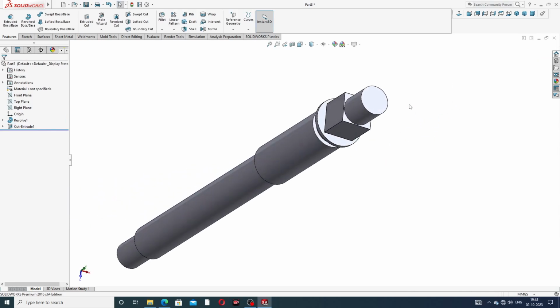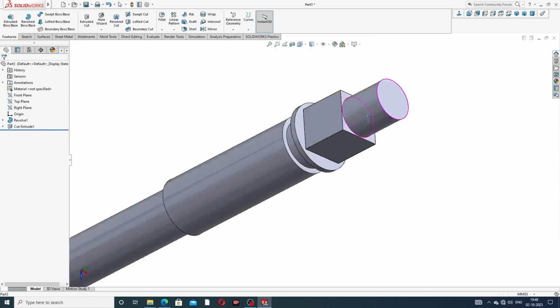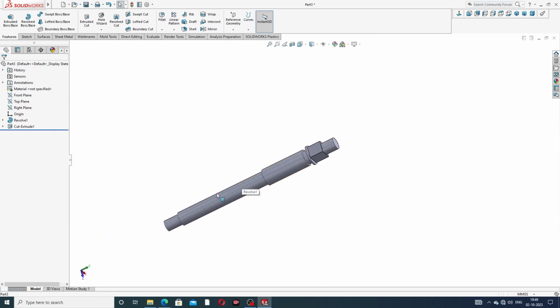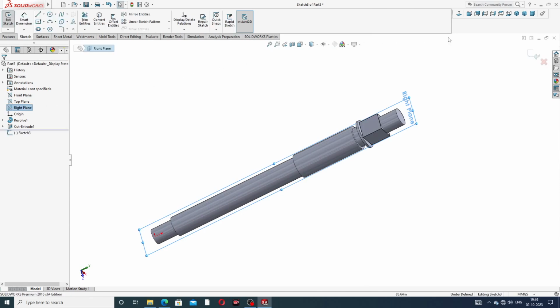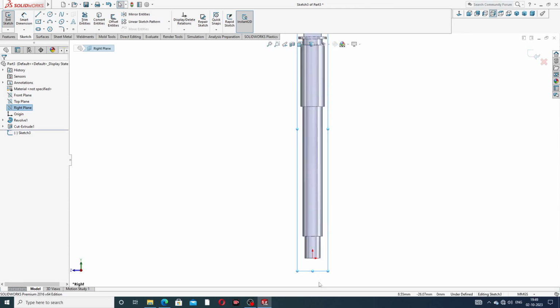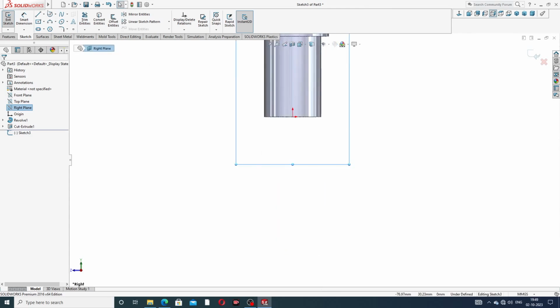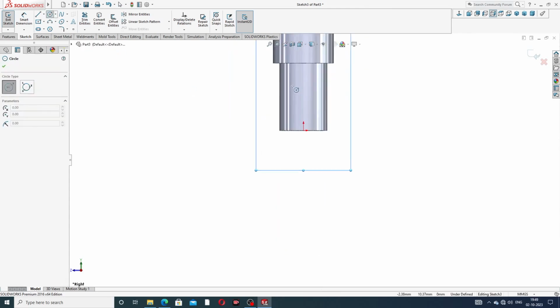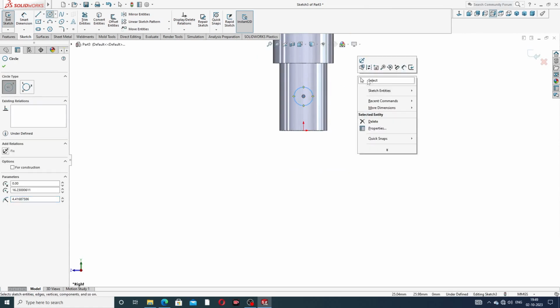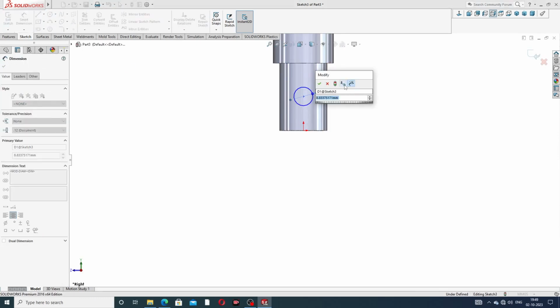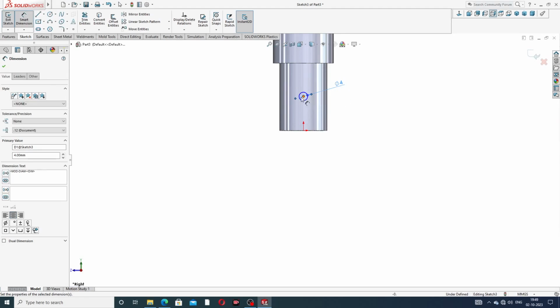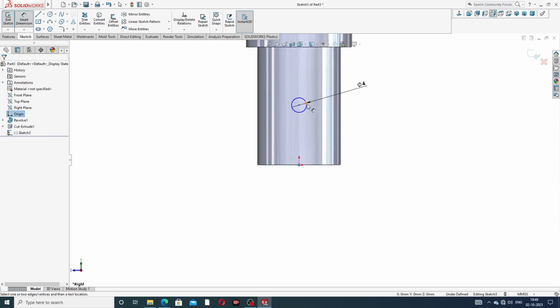Okay, this is very nice looking here, and this is perfect and correct, and also use a right plane, a hole is created here, and drawing a circle, and circle is correct. Okay, and this diameter is a 4 millimeter and this distance is a 9 millimeter, is perfect.